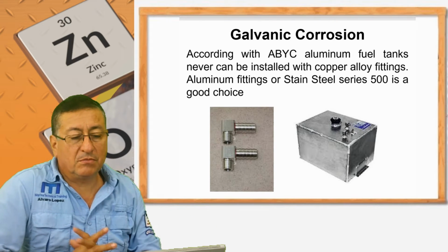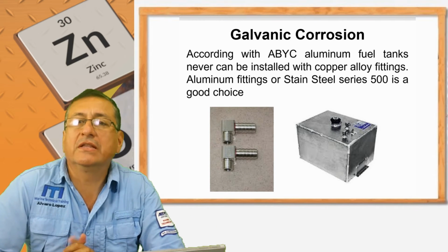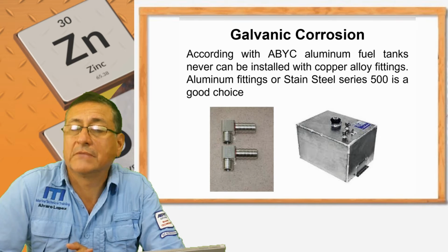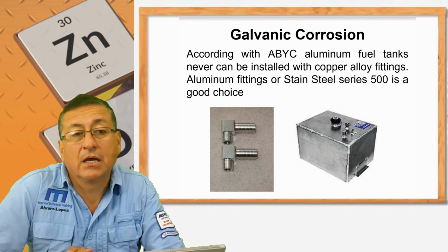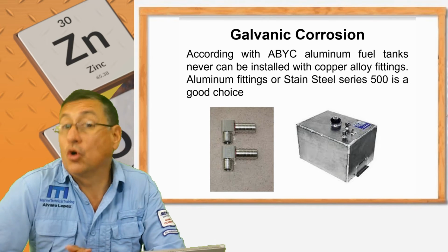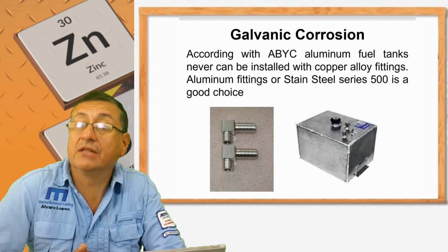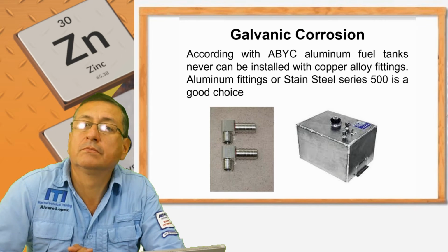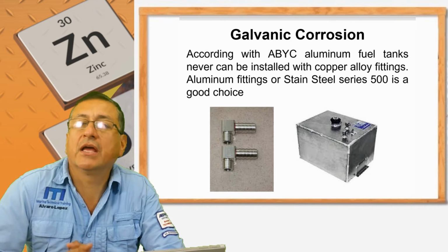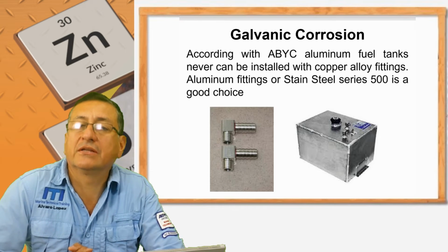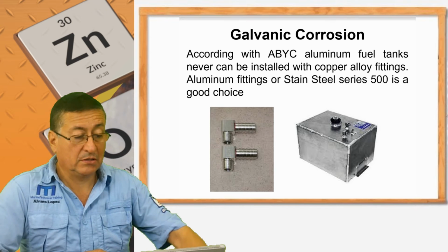Yeah, for that reason, my friends, the selection of the fittings is critical. I have an aluminum tank, I need aluminum fittings, or stainless steel marine grade fittings. Never copper fittings. Doesn't matter if it's a marine grade copper fitting. I prefer, if the tank is aluminum, aluminum fittings or stainless steel Series 300 fittings. Be careful with the fittings.